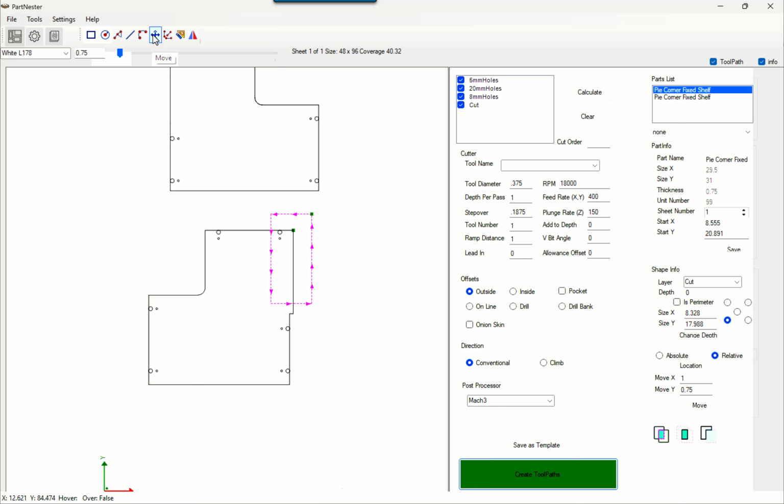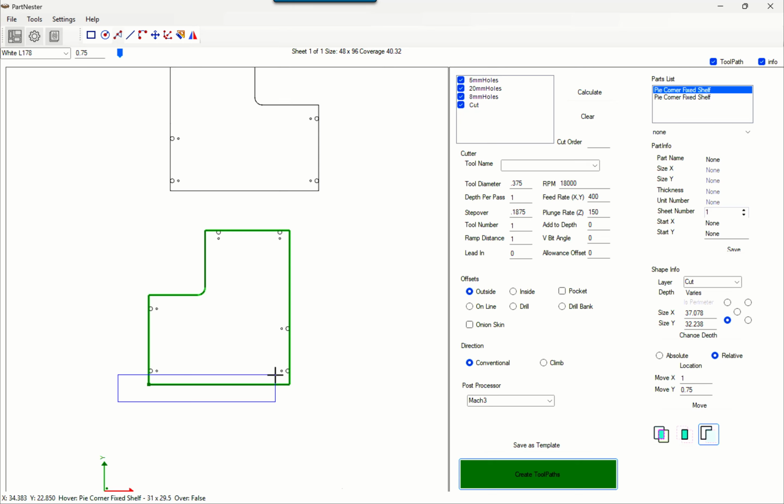I'm going to use the move function. I'm going to move from one point to the endpoint of that rectangle, to the endpoint there. Again, shift, selecting multiples. I'm going to do the same exact thing across the bottom. And again, having the mouse up when it's in the interior will not create that extra part, and will prevent a little bit of a step.